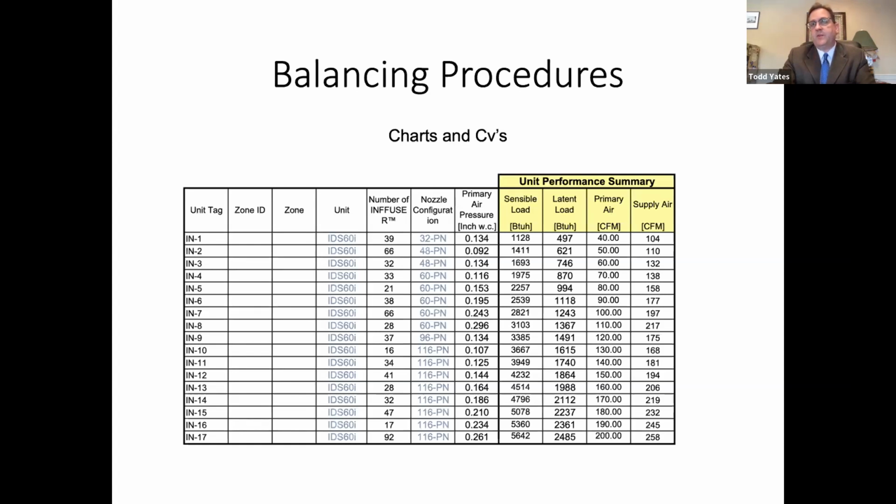One of the things that we did is create a small spreadsheet for a technician on this project so that they could take a reading, put their differential pressure in a box, and they would get the airflow immediately. So they would know what to record for that one, rather than trying to do complex calculations in the field. Even if it's repetitive and simple, that was a tool that we created for this project just to simplify their work in the field.